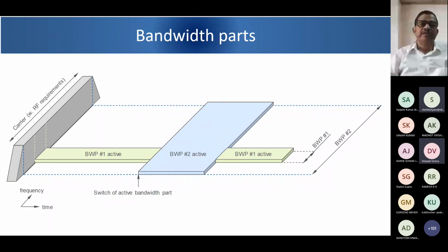Yeah. Okay. Very right. Very good question. So in different bands, these bandwidth configurations are already defined in the standard. Why are these defined? So that while manufacturing, you know what you have to manufacture, right? It cannot be dynamic. Technically you can do a dynamic configuration in the network, but they have given it in the standard itself, so that when you're designing a device, you do not know what kind of network it is. So everybody will configure the same BWP onto the network in different bands, and it can be utilized. Got my point?